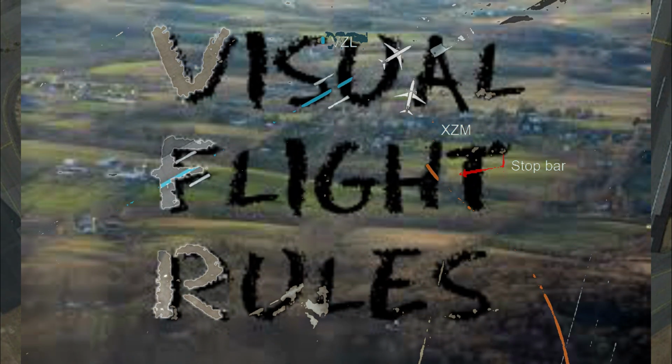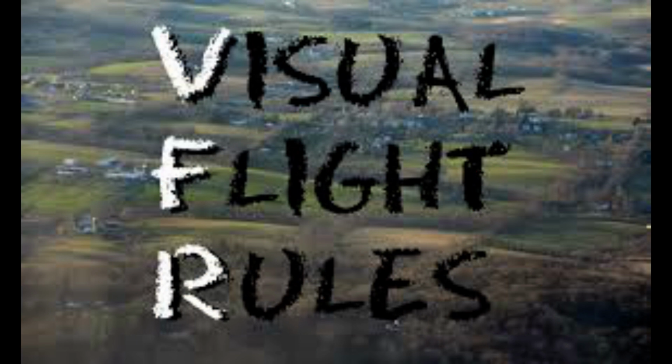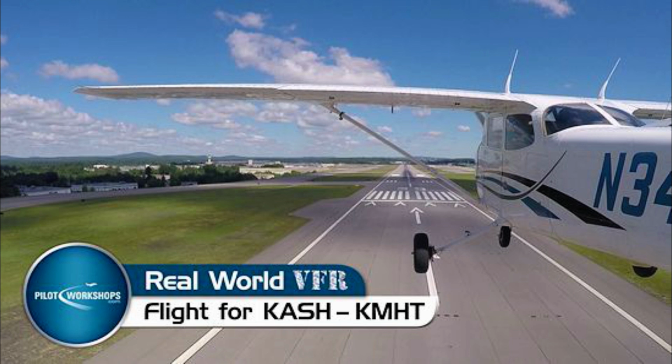VFR departures. There may be times when you need to fly an IFR flight plan due to the weather you will encounter at a later time, or if you simply wish to fly IFR to remain proficient, but the weather outside is clearly VFR. It may be that you can depart VFR, but you need to get an IFR clearance shortly after departing the airport. A VFR departure can be used as a tool that allows you to get off the ground without having to wait for a time slot in the IFR system.